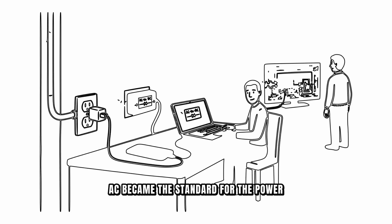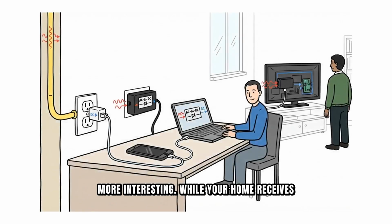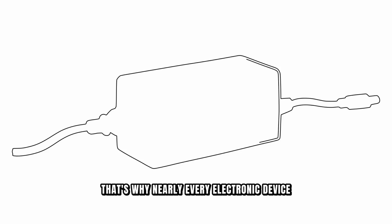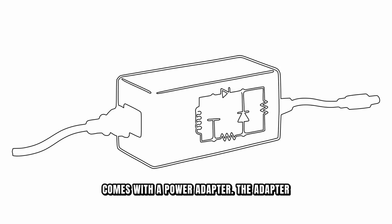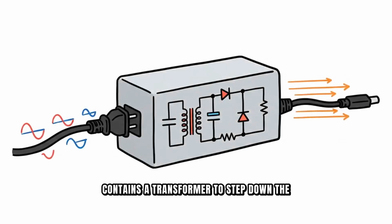But here's where it gets even more interesting. While your home receives alternating current from the grid, most of the devices inside your home actually use direct current. That's why nearly every electronic device comes with a power adapter. The adapter contains a transformer to step down the voltage, rectifier circuits to convert AC to DC, and filtering to smooth out the resulting current.